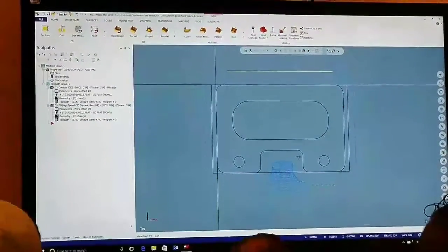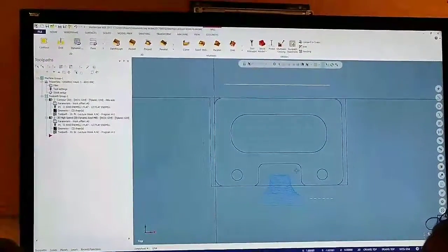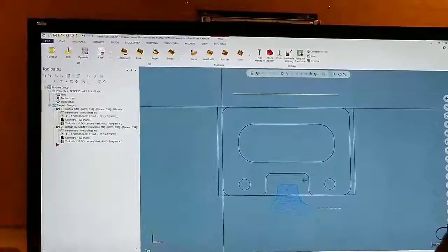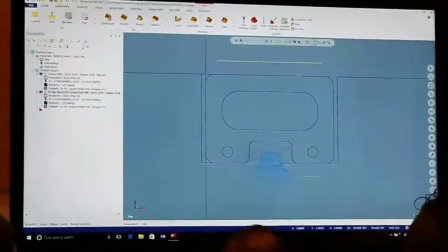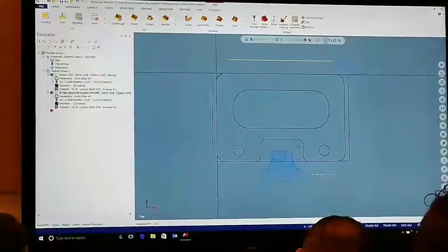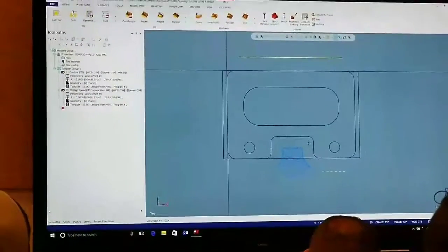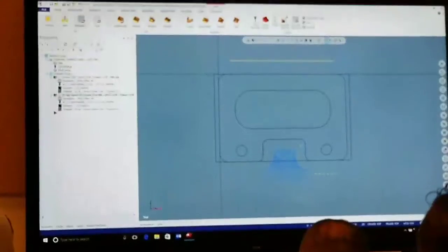Just do a simple contour. And we could just contour around there. When it comes in the corner, it'll just get that material out of there, right? Mm-hmm. But quite a bit of meat there, wasn't there? Yeah. How's that end mill going to handle that corner when it comes into that corner with all that depth and all that tool pressure against it? Is it going to like that?